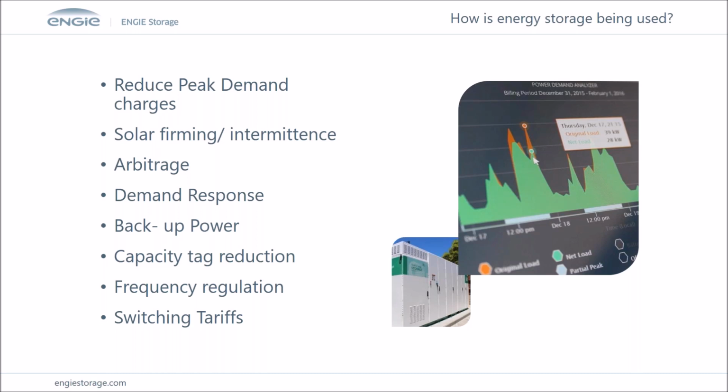So energy storage is a great way to shift load from when you're not using it, typically in the evening, to on-peak timeframes when you do have those higher demand charges. We're also seeing a lot of this combined with solar because of solar intermittency and resiliency and solar firming. We're now seeing about 60% of our projects tied to solar, which creates some financial incentives in many markets and opens up markets that have demand charges usually about $15 or higher. We're also seeing a lot of arbitrage, which I think most people think about.